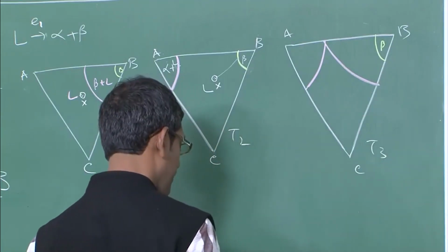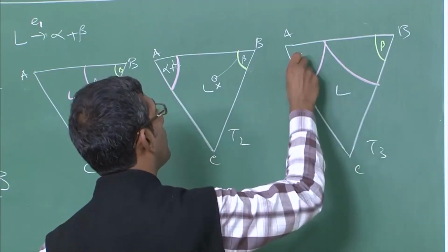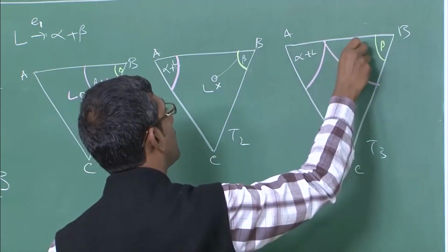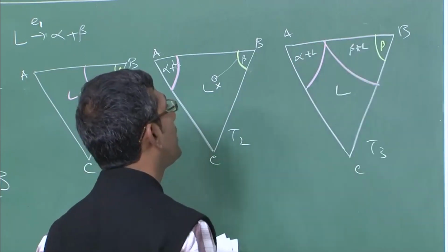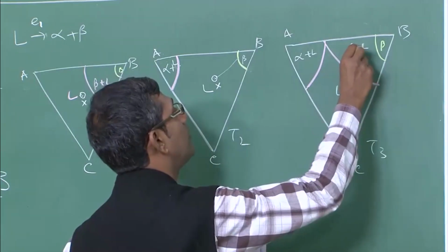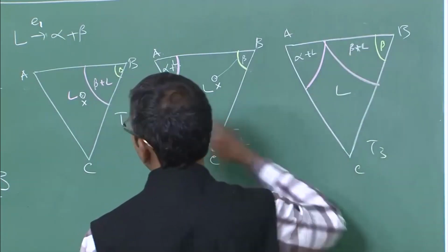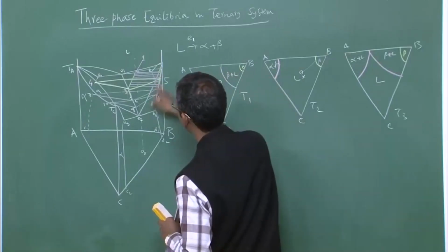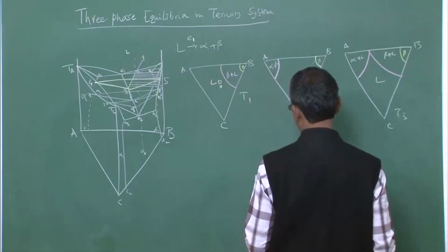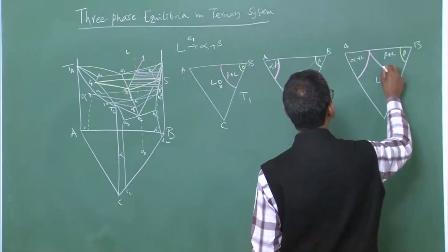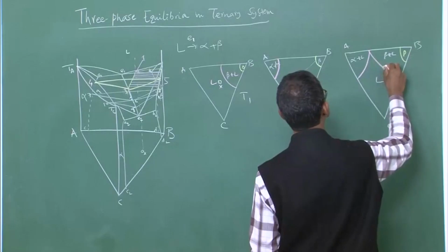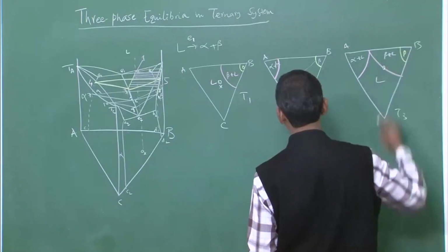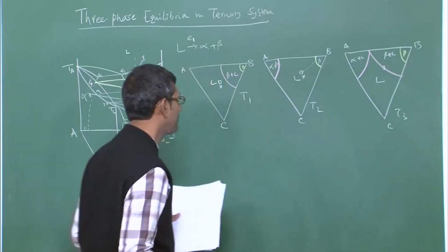Okay. So, what do you have? You have liquid, alpha plus liquid, beta plus liquid. You have a clear distinct beta plus liquid zone developed. That is what is here, the beta plus liquid zone on the right side, and the alloy then sits on this. As it sits on this, it will precipitate more and more beta.